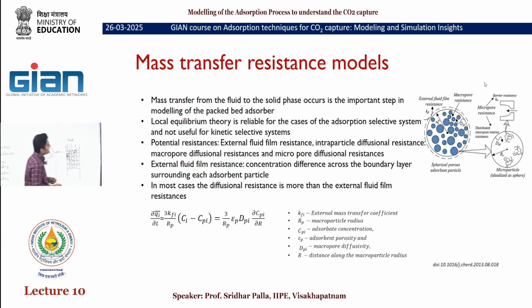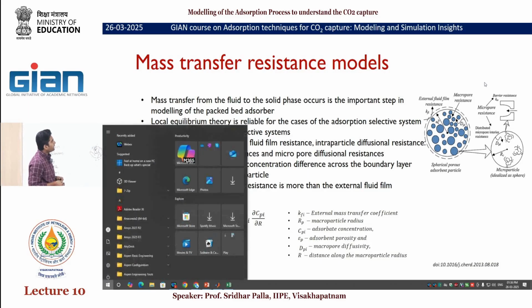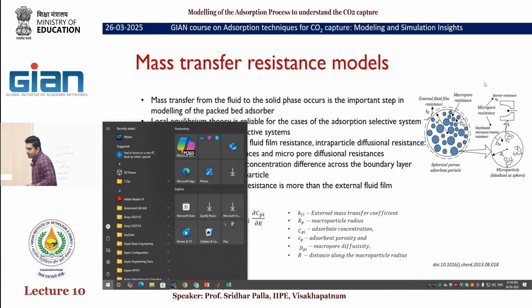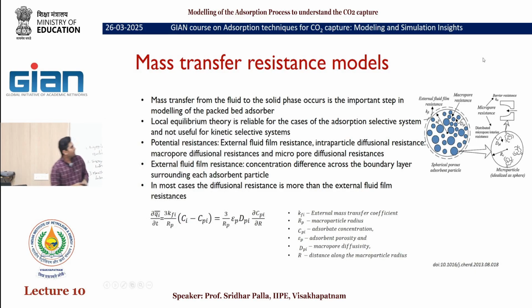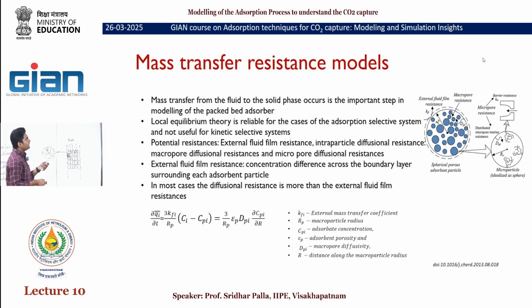Here you have a very nice picture. When there is a gas particle coming here, around this pellet we have a film resistance, that is the external fluid film resistance. If you recollect from Dr. Ravi's talk, there is a film mass transfer coefficient that we will also use. Inside this pellet we have these macropore resistances, how the gas molecule will diffuse through the pores, the macropores.